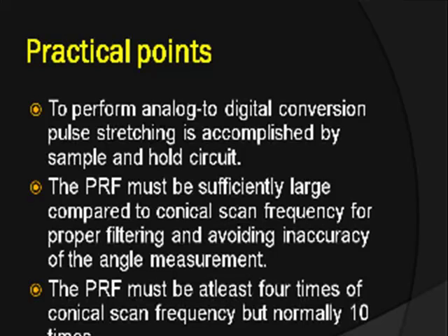The PRF must be sufficiently large compared to the conical scan frequency for proper filtering and avoiding inaccuracy of the angle measurement.